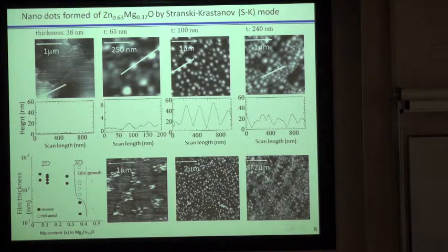It shows coherent growth, and above such a threshold thickness, it shows these kinds of quantum dot structures. Therefore, when we like to form quantum wells, single quantum well, or multi quantum wells, we have to set the composition and the thickness around these growths. And of course, when we like to form the quantum dot structures, we set the conditions around what is shown here.